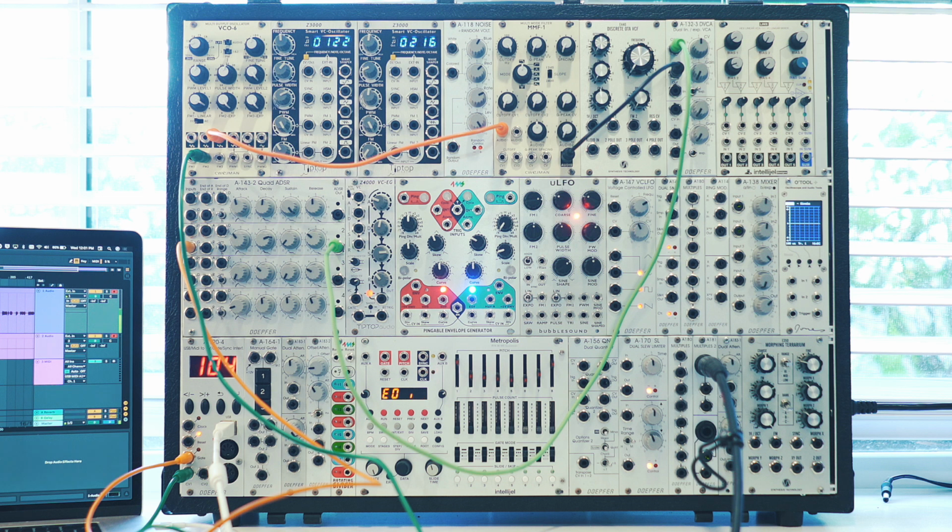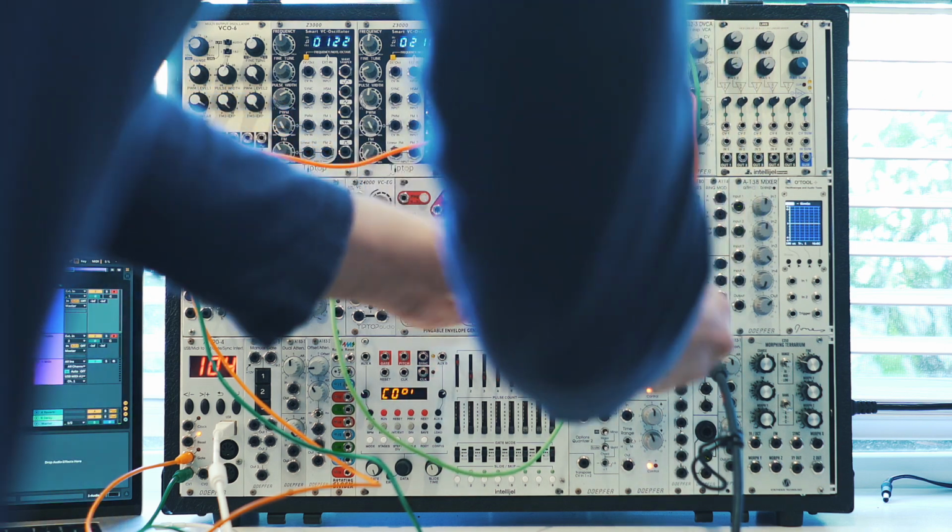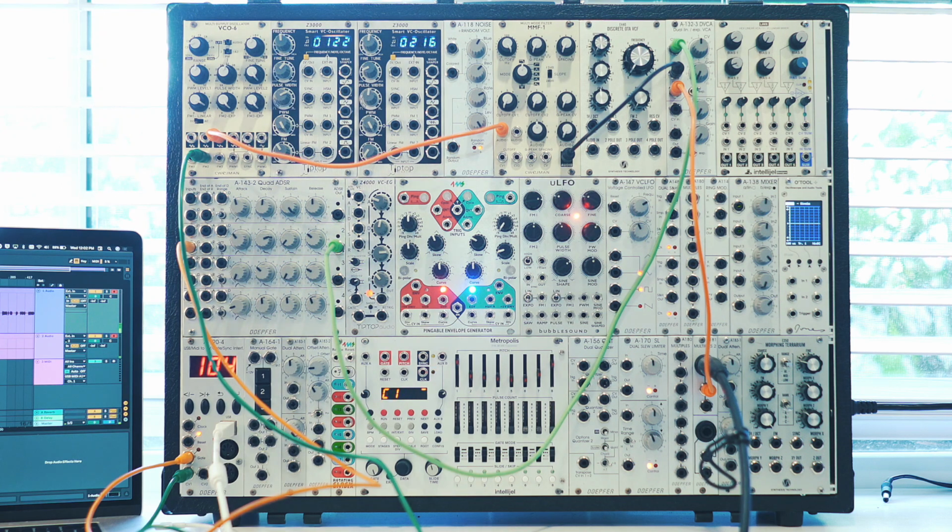So now let's take the output of the VCA and we can plug it into the monitoring system. My monitoring system is going out on that 1/4 inch jack on the multiples. So I just need to take the output of the VCA and plug it into the input on the multiples. Now keep in mind this signal could be quite hot. So you may want to use an attenuator first to tone down the level of the signal, or use an external mixer to control the level. But if I play on the keyboard now, you should be able to hear the sound.